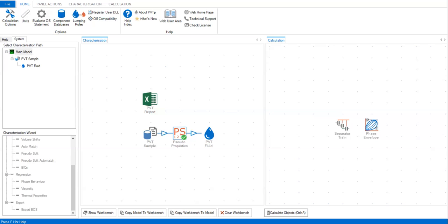Okay, so here we will utilize the binary interaction coefficients in expectation that we can improve the quality of the match, especially for the calculated saturation pressure. By the way, with this in mind, there is no direct need for the use of binary interaction coefficients, actually. However, they could still be used, although with very small values, but we can use them to provide the regression with additional degree of freedom, additional flexibility.